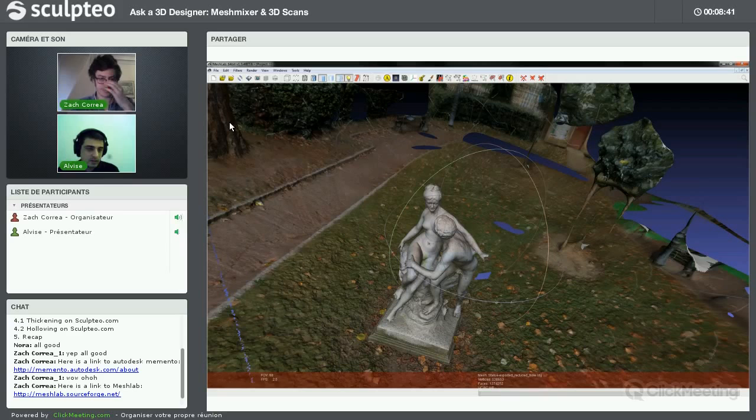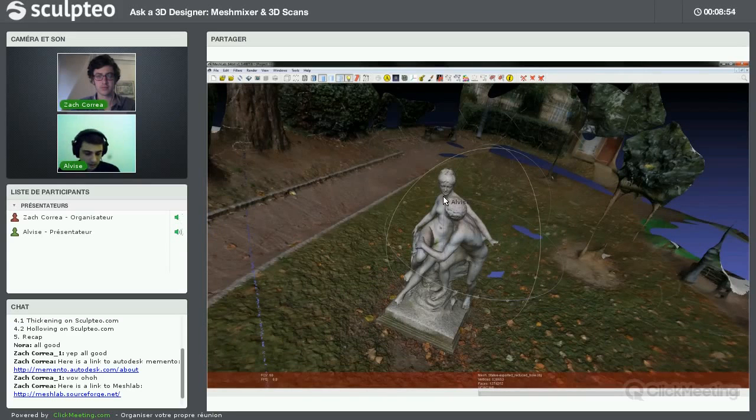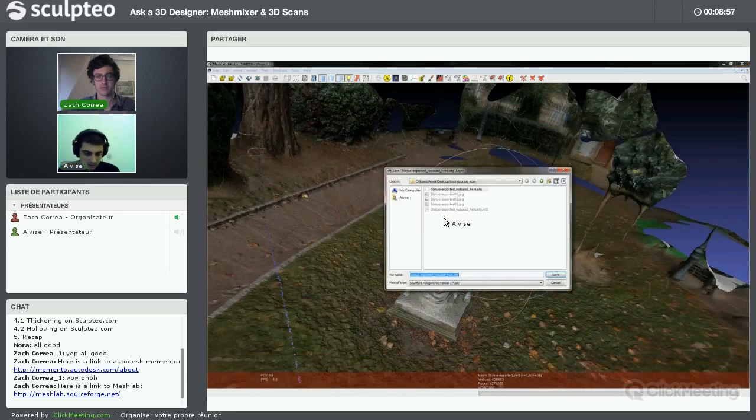It's good for MeshMixer, so we can export. We can export this mesh, Export Mesh As. We're going to use an OBJ extension, and I suggest creating a new folder. I'm going to call it the same but reduced, and put the statue reduced OBJ file in this new folder. Be sure that color, texture coordinates and normals are selected, and OK.